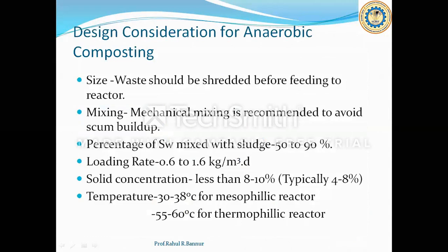Design considerations for anaerobic decomposition. Size: waste should be shredded before feeding to the reactor. The size of the solid waste should be between 25 to 50 mm. Mixing: mechanical mixing is recommended to avoid scum buildup. The percentage of solid waste mixed with sludge is 50% to 90% to boost up the reaction.